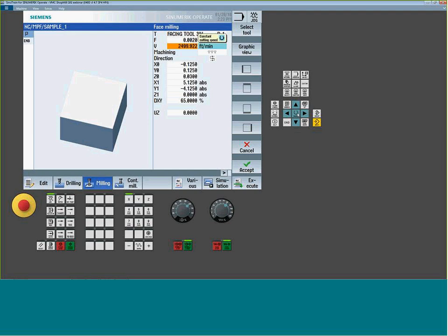So if I look at my insert pack and for a given recommended material, maybe it says that I want to run at a feed per tooth of 3.5 thou, and a surface footage of, let's say, 1800 for that tool and that material. Now if I toggle back to the feed rate, the system will even show me the calculated feeds and speeds for those cutter parameters.